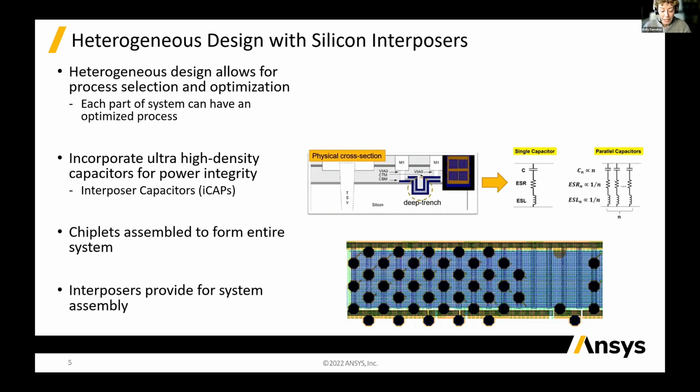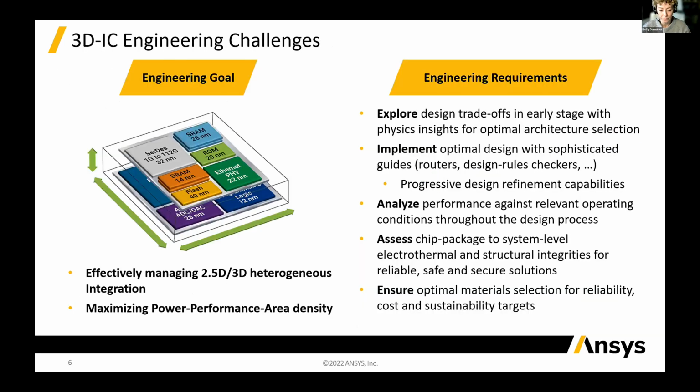Heterogeneous integration implies the addition of analog signals to custom chiplets like wireless communication and sensors. In order to achieve the optimal power, performance, area, and cost trade-off, engineers need to start the exploration of alternative architectures earlier than with monolithic SoCs, in the design cycle that they traditionally use.